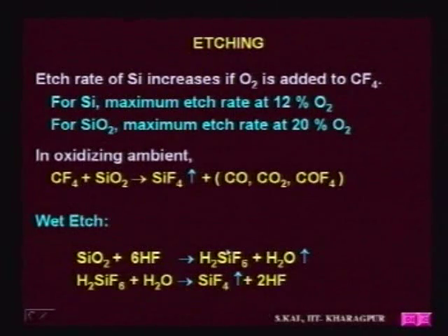At the same time, in the wet etch process, the problem is the hydrofluoric acid consumption: you see 6 HF ultimately end up with 2 HF, that means its concentration reduces. So, the etch rate will obviously lower if you etch for a longer time, isn't it?